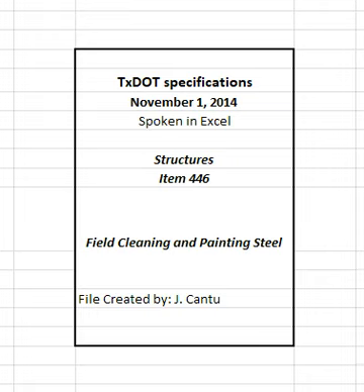Apply all coats by spray, except brush-applied stripe coats. Obtain engineer approval for alternative methods of application to paint inaccessible areas. Repair all runs, sags, and other defects in each coat of paint before application of subsequent coats. Measure the dry film thickness of coatings in accordance with Tex-728-I.